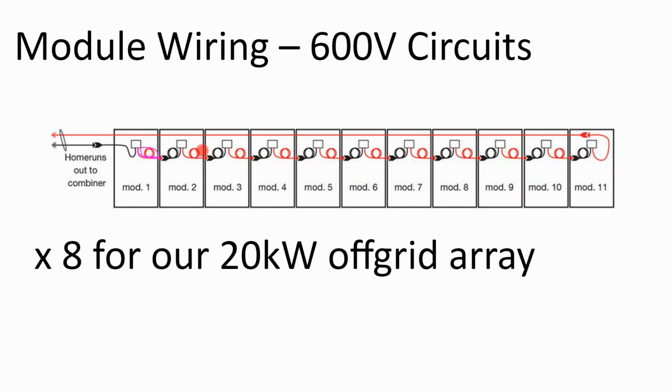Now you see all this extra slack here. That's because these module whips are also designed to plug in a landscape configuration as well. So if you install in portrait instead of landscape, you're going to get a bunch of slack. The reason I mention that is if you have a slightly taller solar panel, you have a slightly longer module whip.